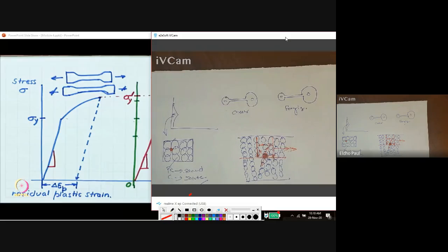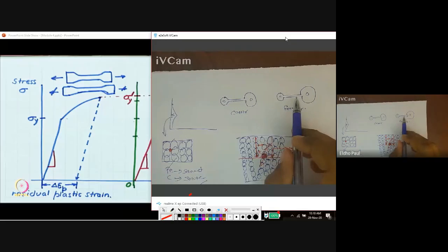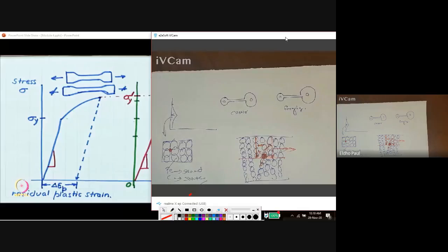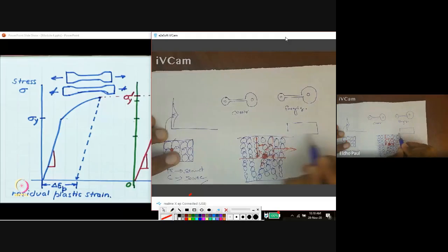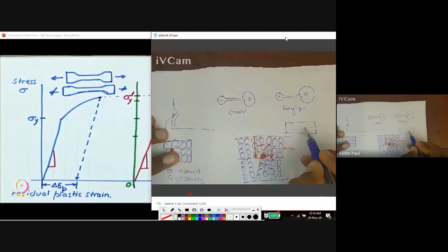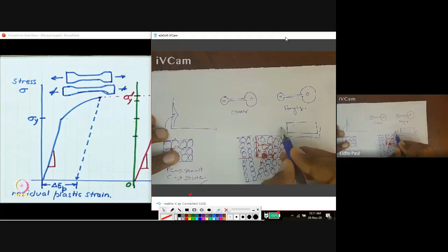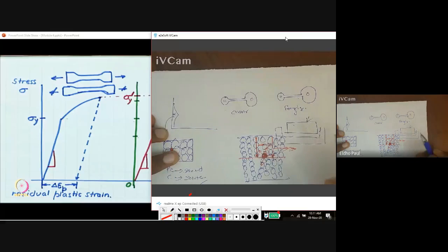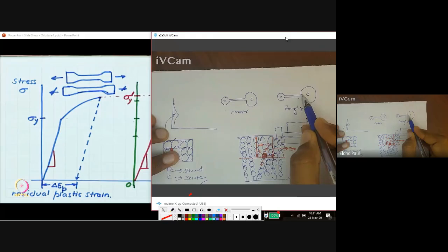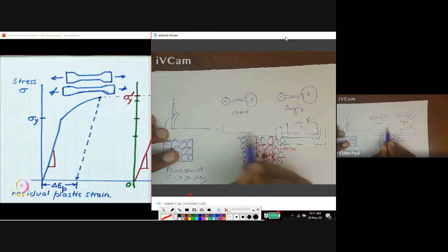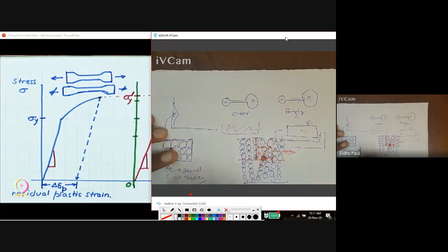Yes, the forged one is actually a plastically deformed workpiece. In the forging process, we keep the raw material on a die and apply a compressive force, and this workpiece changes to connecting rod shape. But in the casting process, we solidify the molten material.